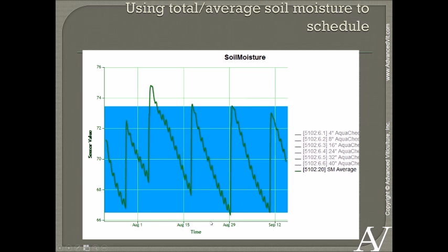In Ranch Systems, we can put in a band, and I like to put the band where those reference lines were in that previous slide, where this is our refill point and this is what we call a full point. We try to keep it within that band. Now that's not what people call deficit irrigation. I'm irrigating it and keeping it more or less at the same water status level here.